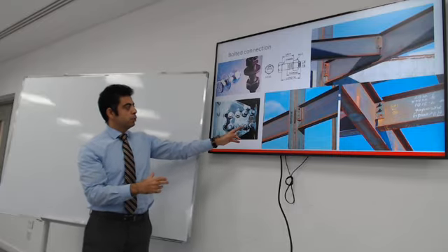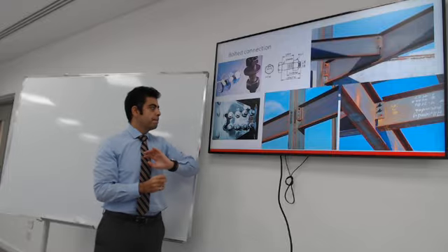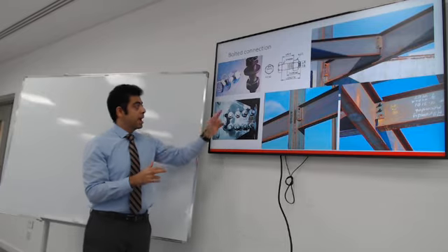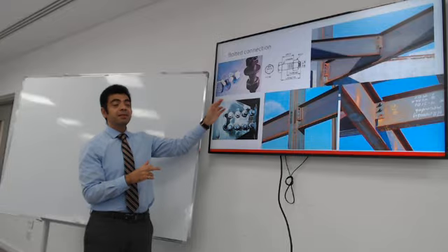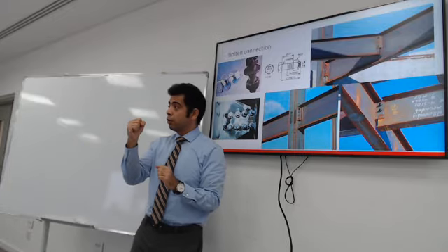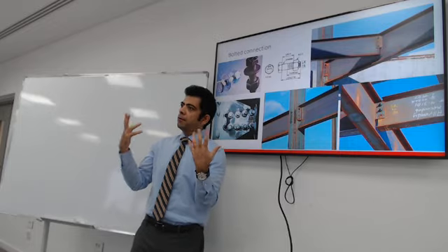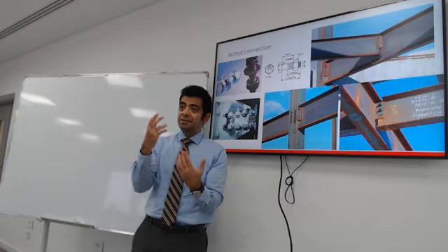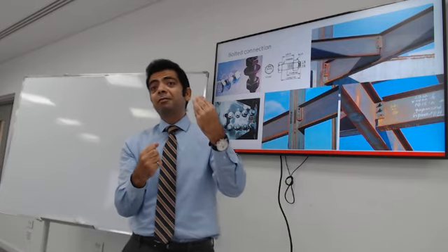The individual bolts managed to withstand the load, but the failure actually happened in the steel. So choosing a very strong bolt will not guarantee a very high strength for the connection. You need to manage two things: the strength of the bolt and the strength of the steel.